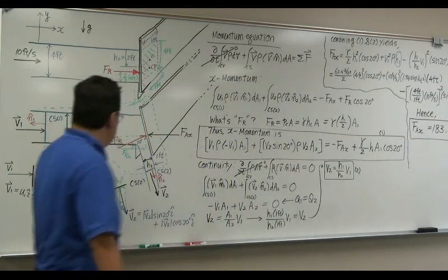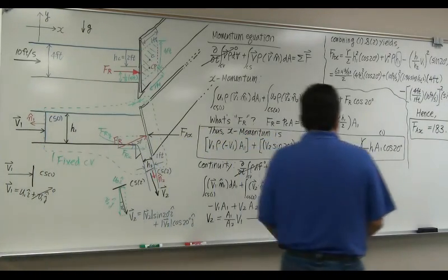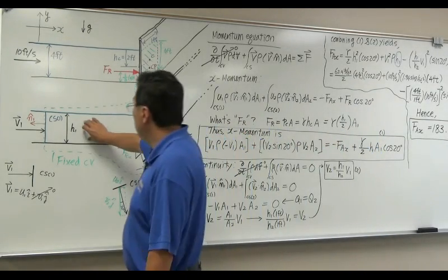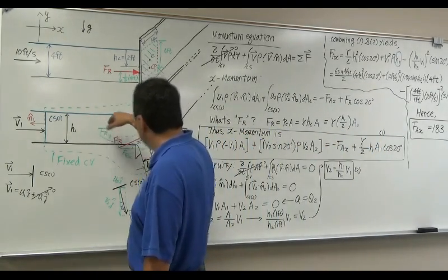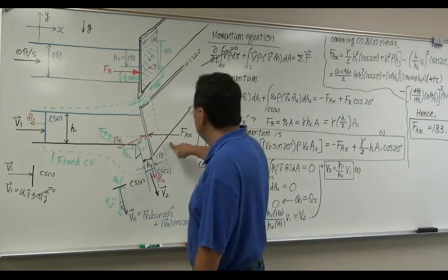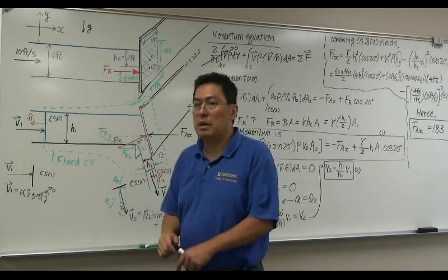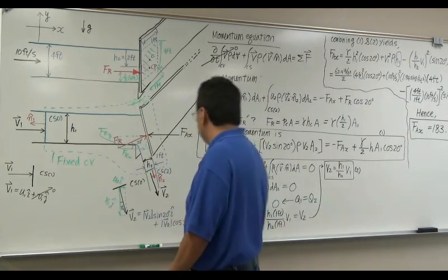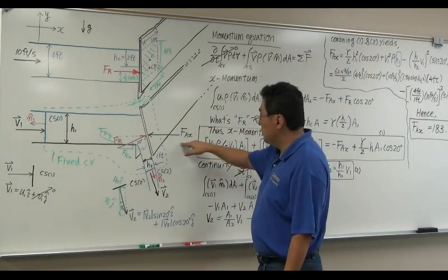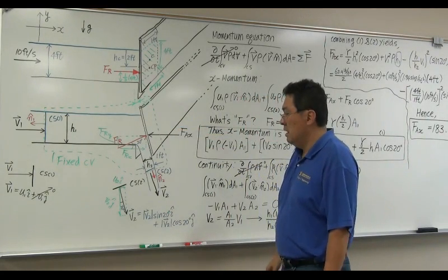FAX is essentially supporting FRX and also the X direction component of momentum change, both. Now, if I include the weight of this liquid, that actually contributes to the Y direction component of the force. So FAY is essentially this one plus the Y direction momentum change based force development. But this is particularly a problem interested in how much force you need to support this plate in place. Now keep that in mind.